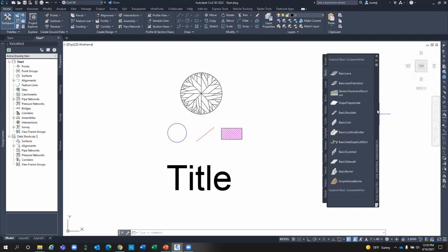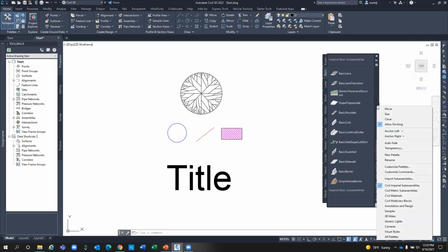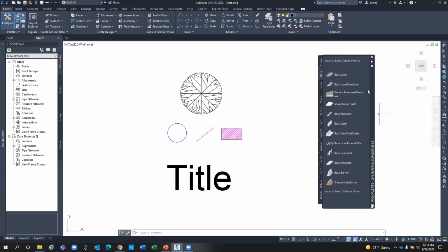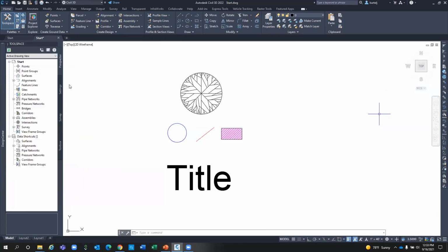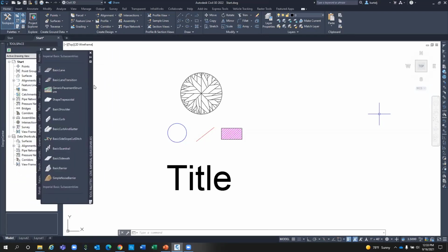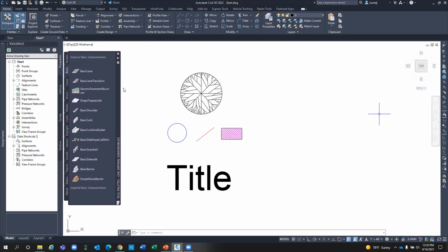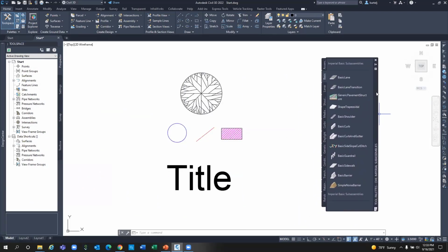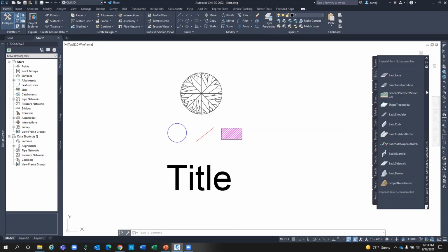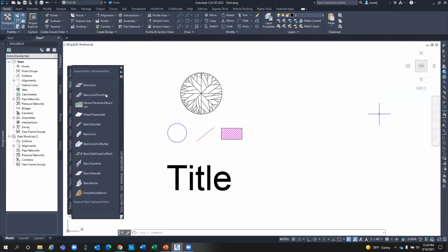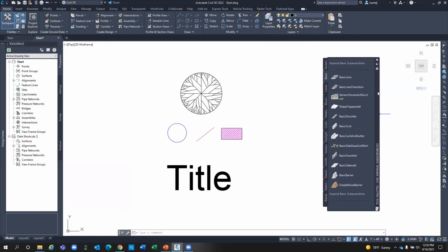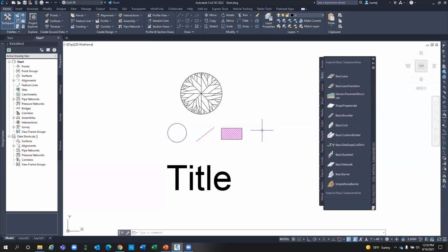Speaking of docking and where it might go, think of it like the Properties palette. We've got tools that we can anchor it left and right. You can add transparency. You can do auto hide. We can even, as you click and start moving it around, you'll see as we get close to particular areas, it starts to dock. One thing that's always helped me, especially with screen real estate, sometimes if you're moving palettes around to have it closer to the area that you're working with, it has a tendency to want to dock, maybe if you don't want it to. If you hold down the Control key, you can move that palette anywhere you want, and it can't dock as long as Control is down. So keep that in the back of your mind.